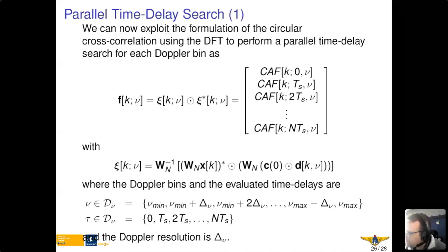In general, you can understand that for the relative velocity between user and satellite, we have rough estimates. If the user is not moving, then a Doppler search between -6 kilohertz and +6 kilohertz is sufficient. If you are moving also, then you have to take this into account. But anyway, we end up with a limited search space for the Dopplers, and then you only need to decide on the resolution of the Doppler for your acquisition.